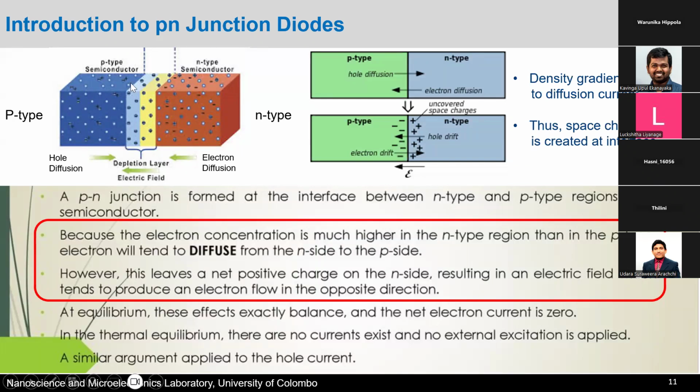In the same way, the boron atoms have the negative charge, right? And it has basically now become an ion. So the boron ion is also fixed to the lattice, and once the holes are moving to the right-hand side, it's exposing all the negative charges on the left-hand side. So what you actually have is a particular electric field that's going from positive to negative charges, right?